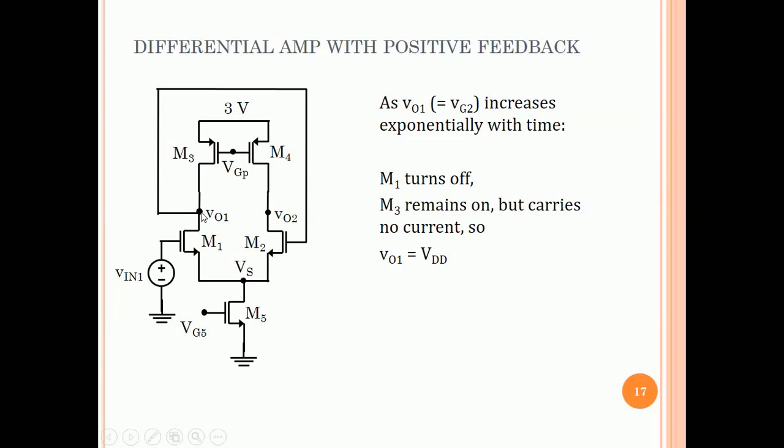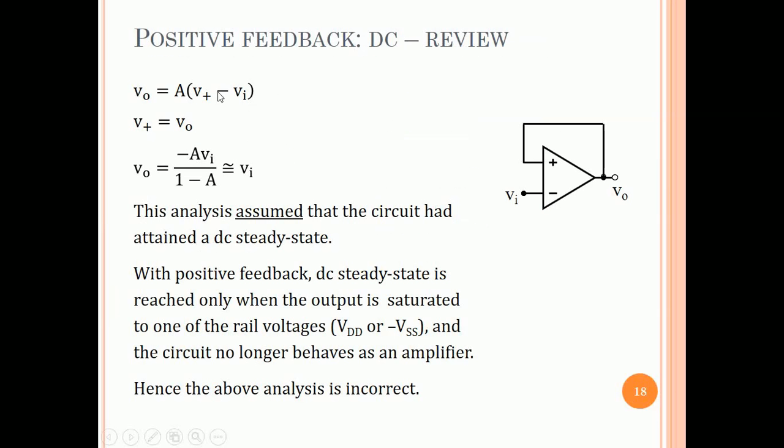So the equation, alright, so let's go back to the DC. So when we derived these, this is the DC equations we wrote, and we say, well, VO is equal to VI. For deriving this, there were two assumptions actually. One was that the circuit had reached a DC steady state, and the second was that in the DC steady state, the amplifier had a high gain A. Alright.